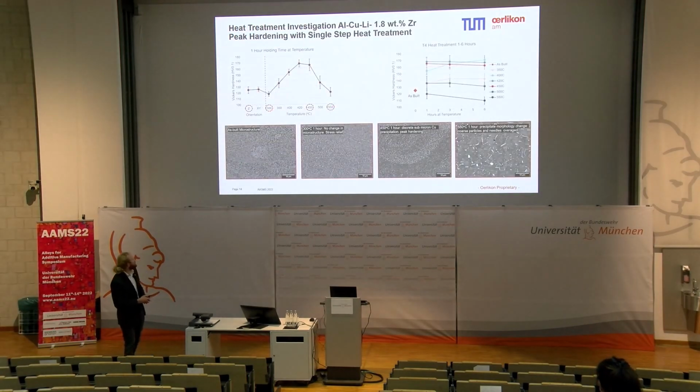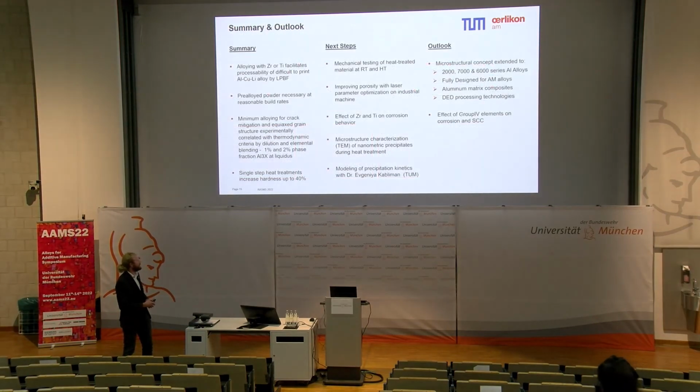I think I'm running out of time, but quickly, we've also done some heat treatment studies, basically to try and find a peak hardening condition, both with constant holding time and also isothermal heat treating. We've gone to a higher temperature regime, because of the effect of those aluminum-zirconium precipitates, which we know from the literature and Thermo-Calc are quite stable. Currently there's tensile testing underway. I can say we're also applying a similar concept to other alloy systems, and also DED, so different processing technologies.